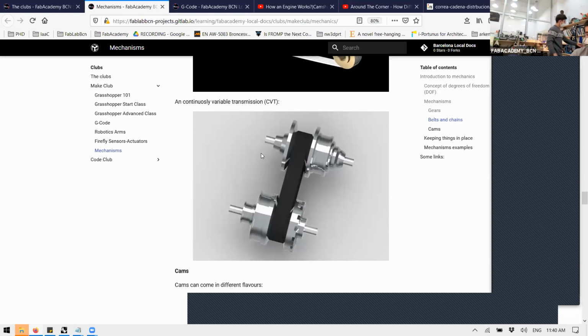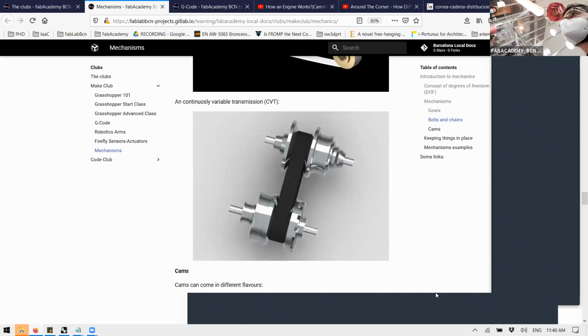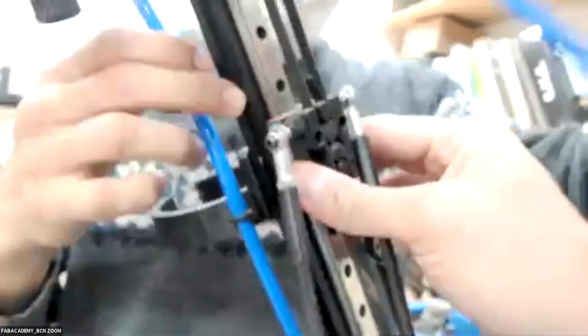These belts, for instance, in this one, these are the timing belts. We have a pulley in here on top. You have a pulley here and the stepper motor down here. And this is the timing belt that is attached to this part. And then here you have a rail with a bearing. And in this case, it's a linear bearing that stays on the rail. In this case, this other machine has the same as that one over there.